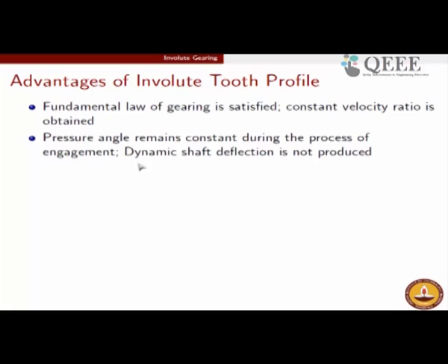That in turn means that the pressure angle is also fixed during the engagement, because pressure angle is basically the direction of this common normal with respect to the tangent to the pitch circle, and since the common normal has not changed, pressure angle has not changed.